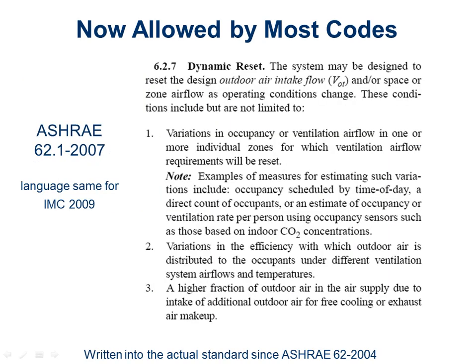So here's what it shows you for ASHRAE 62. That's specifically called dynamic reset. And this is basically how it works. This is the same exact language that's in the International Mechanical Code. And this is what's basically allowing me to ventilate based on the CO2 levels.